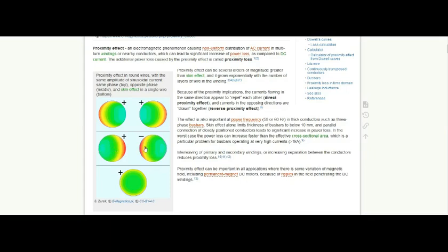But that's something to determine and to see whether that does that, and hence greatly improves the Q factor. If you had another one here, for this one there, it would end up looking like that. Then if you had that set up, that's when you would use your Litz wire to also mitigate skin effect.